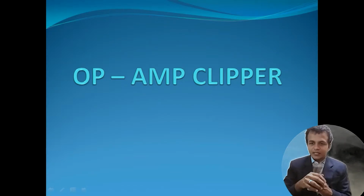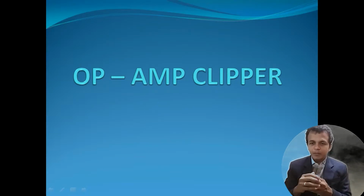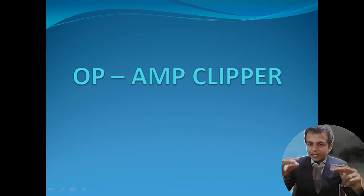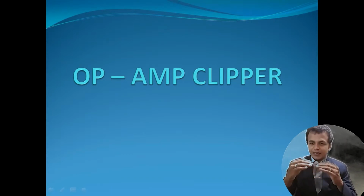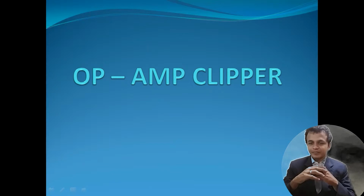According to this, clippers can be classified into two types. One is the positive clipper, another is the negative clipper. In a positive clipper, the portion of the input waveform above the reference voltage is clipped off, eliminated. Whereas in a negative clipper, the portion of the waveform below the reference voltage is completely eliminated.